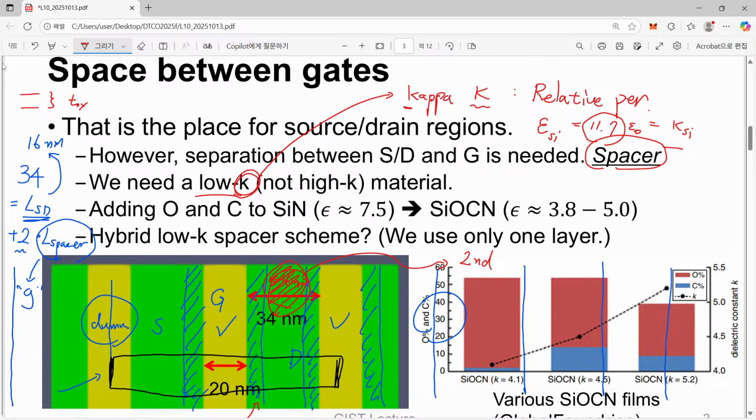If you remember correctly, if we wanted to have higher and higher oxide capacitance C-ox, that is given as oxide permittivity divided by oxide thickness. In order to achieve this goal, engineers reduced the oxide thickness continuously, and when it became around 1 nanometer, they found that now the oxide is too thin, so our electrons